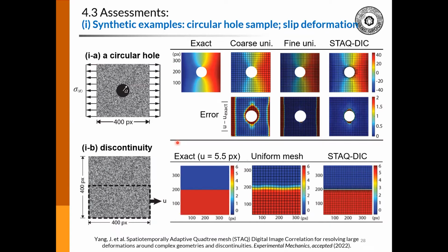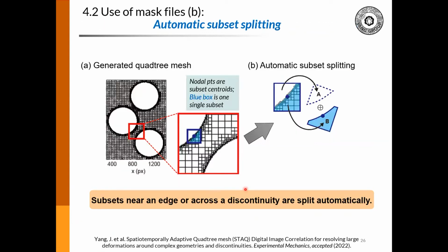Oh, that's a good question. Let me go to one of the pages so I can answer some of your comments. First of all, all the nodal points have been spatially refined, right? But each nodal point has a subset around it. Even though they have been refined near the high curvature areas, with smaller elements, behind each nodal point there's still some size for the subset there.